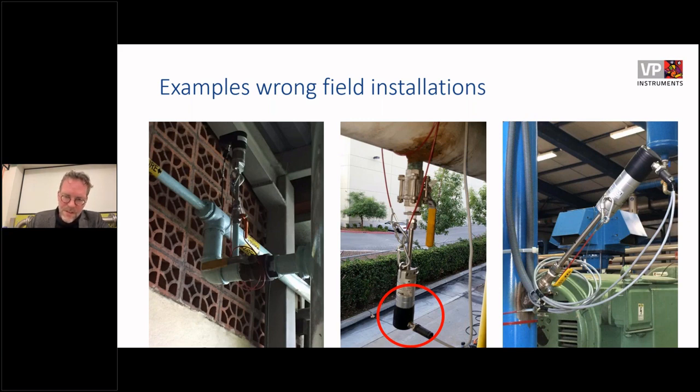The right one, that's a flow meter that someone installed under a big angle in a vertical pipe. Very creative, but not the way to go, because in this case, if you use the triangular formulas, you will see that it will basically show a lot less than it should do. So it's nice to have sometimes a little angle to get the water out of these differential pressure meters, but this is really exaggerated. So don't do this, please. And most of these things you can find, of course, in the user manual that the vendor will supply, and then you can prevent these kinds of mishaps.